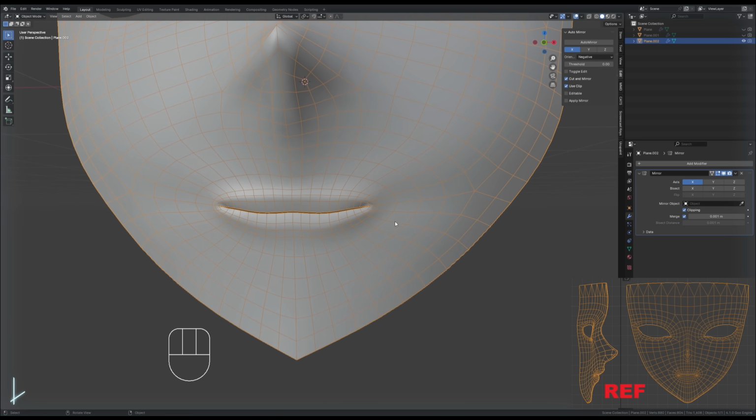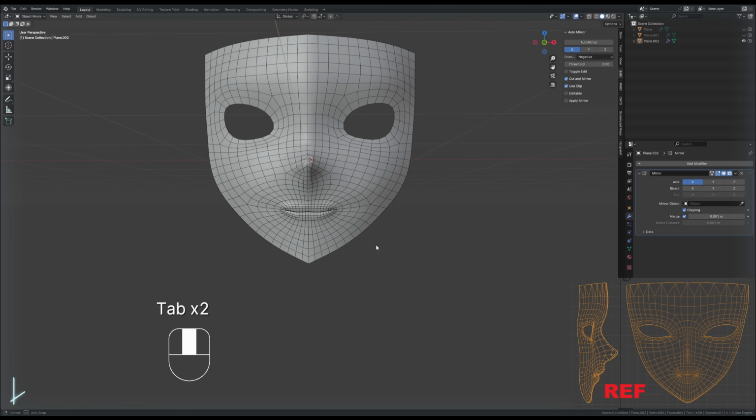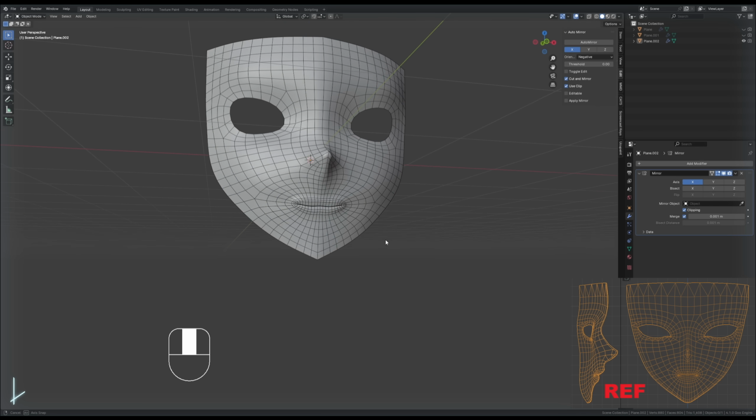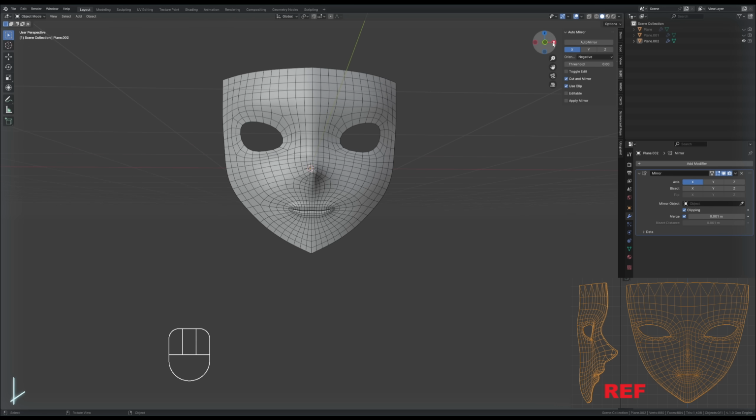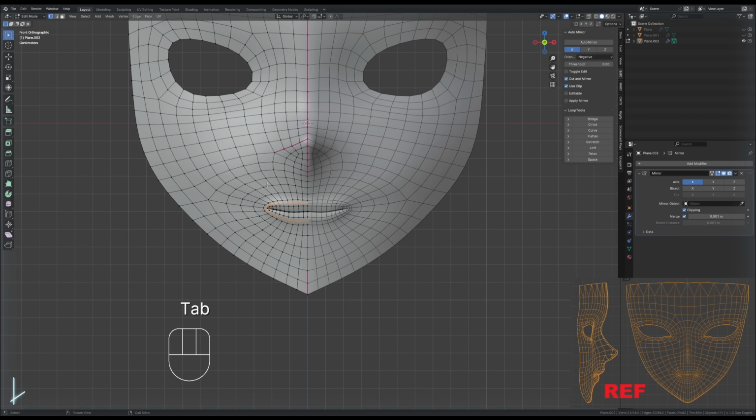The process up to this point can be followed step by step, but the next phase is art style specific. So focus more on the mindset and adapt according to your reference and target art style. For example, now I'm gonna cull some edges to match the mesh that I'm referencing. So I dissolve this edge right under the nose loop, slide in the surrounding edge to average out the gap that was created. And I'll also cull one vertical edge, making sure to select through the mouth too. And as always, slide it to even out the spacing.